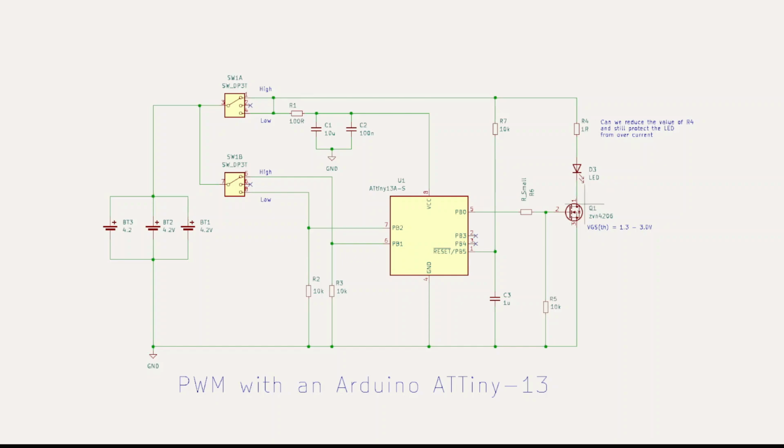So with a fully charged battery, it'll be nice and bright, and with an almost flat battery, it's going to be a lot dimmer. So that put paid to using the ATtiny as my solution. As you can see, I also did a bit of filtering on the supply to keep it away from the pulsing of the LED, but it didn't quite live up to how I wanted it to work, and so again that design landed on the toy room floor.